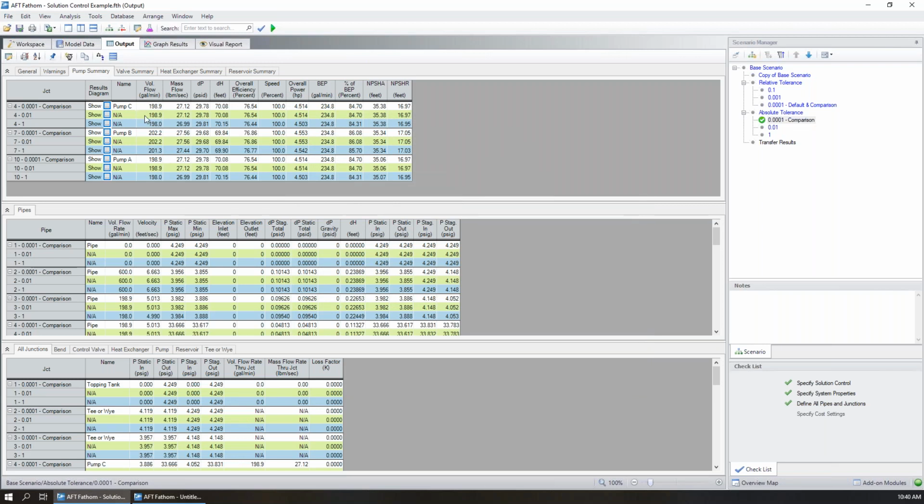So here we can see they're actually pretty close. That might be because our flows are relatively low. For how high of a flow rate we have, 1 gallon per minute or 1 foot of head might be a reasonable tolerance. Again, this requires that you know the flow rate going through your system beforehand. Otherwise, absolute tolerance may not be super predictable or very useful for determining results. So while there are differences in this specific case with absolute tolerance, the big changes are relatively negligible to results.